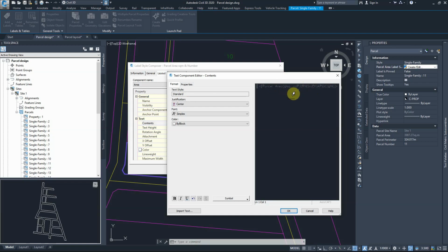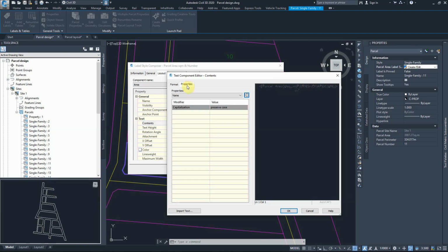That's all we are after. Go back to the property of that, and we'll check it's reading the area for precision of 0.01. We don't need that. We need it to a precision of 1 only. We need the figure to be rounded to the closest full square meters, and the value in square meters, that's what we want. So we'll go OK.